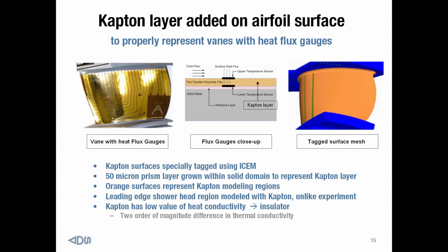But these last two, the boundary conditions and the critical features not modeled, these turned out to be big ones. I mean, for boundary conditions, you could have some kind of idealized solver, but if you put wrong boundary conditions into it, you're going to get garbage results out. And similarly, if there's something important going on in the experiment that you're just ignoring for whatever reason, it's going to be very difficult to capture the correct results. So more on this critical feature.